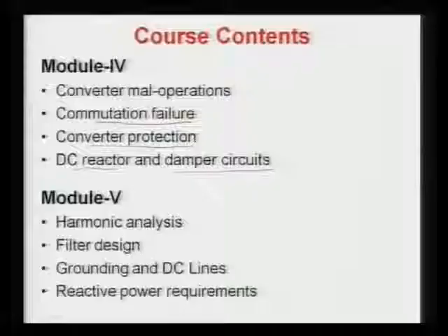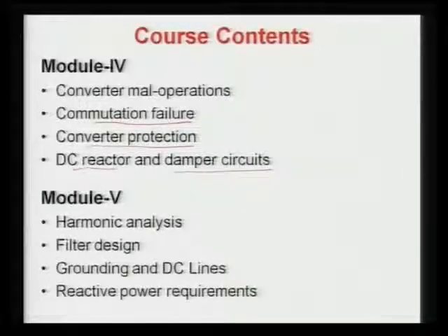The various harmonics, that is the characteristic and uncharacteristic harmonics, are discussed and analyzed for the 6 pulse operation as well as the 12 pulse operation of the HVDC link, and based on that we are going to design the filter circuit. So, we will see the various options, that is a tuned filter circuit, or a band pass filter circuit design. So, the design of the filter will be done in this lecture.